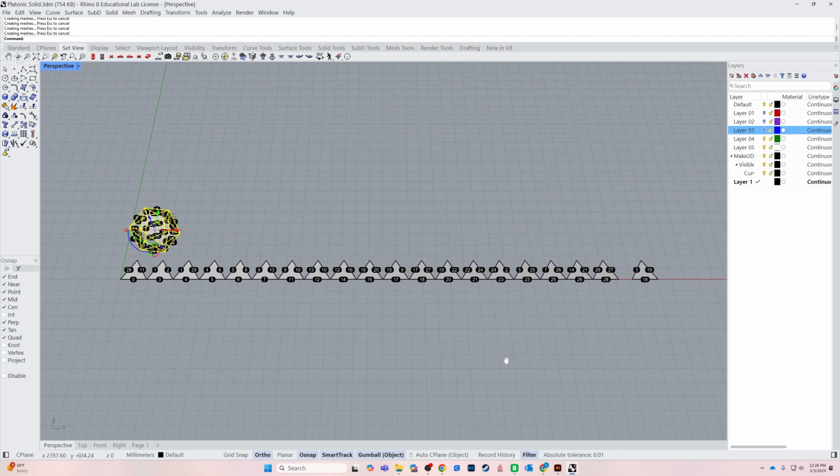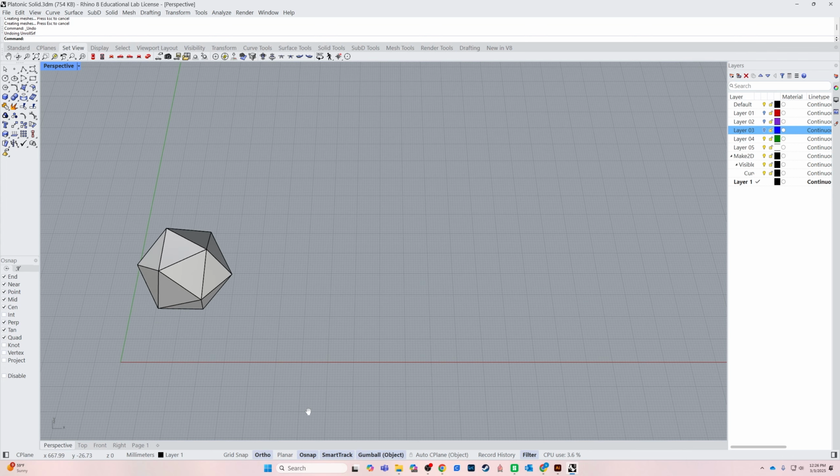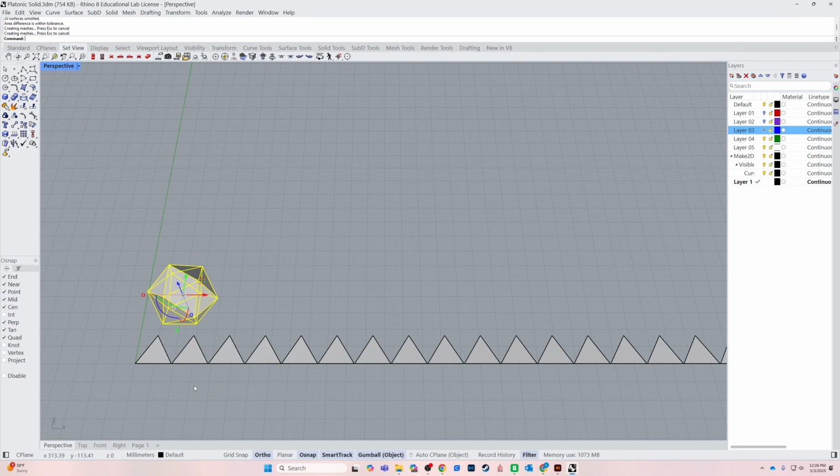The platonic solids that I recommend using usually have the exact same sides, which makes things a little bit easier for laser cutting and creating your object. Okay, so next I'm going to unroll surfaces here. Since my object is platonic and it's all the same on every side, I'm going to get rid of the labels. I don't need the labels. I'm now going to unroll the surfaces here.